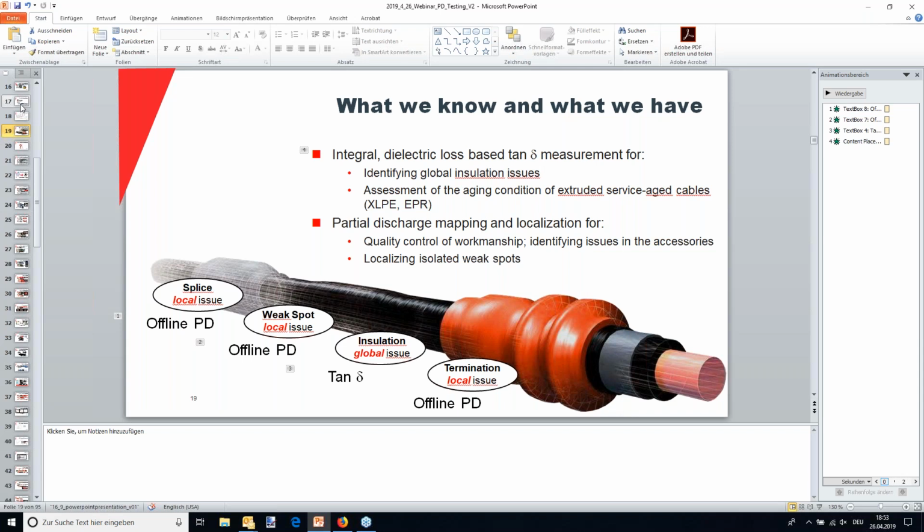The UHF uses UHF-like antenna or radio frequency, and that is a spectrum analyzer really. And that is for the higher voltage environments, high voltage substations and end terminations and all of these things. So there's a distinct application difference: PD scan for medium voltage switchgear, and the UHF, as we call it, or the method is called UHF detection, that is for your substations and transmission substations.